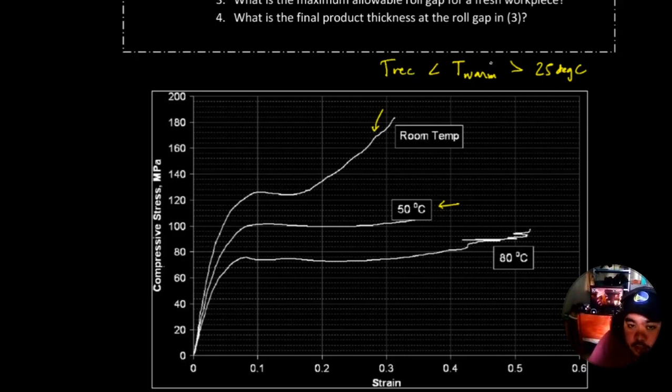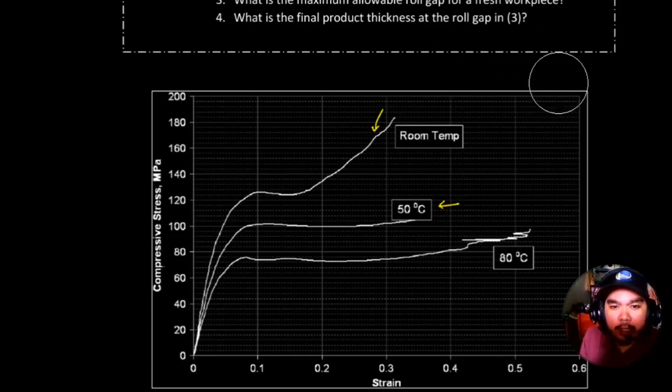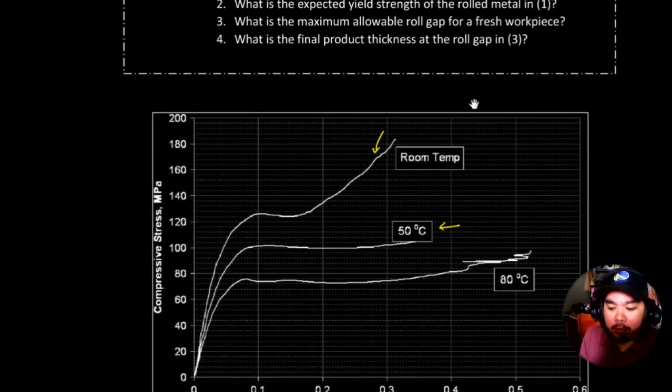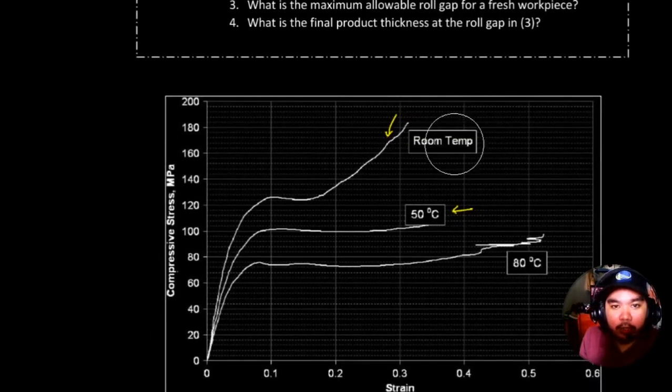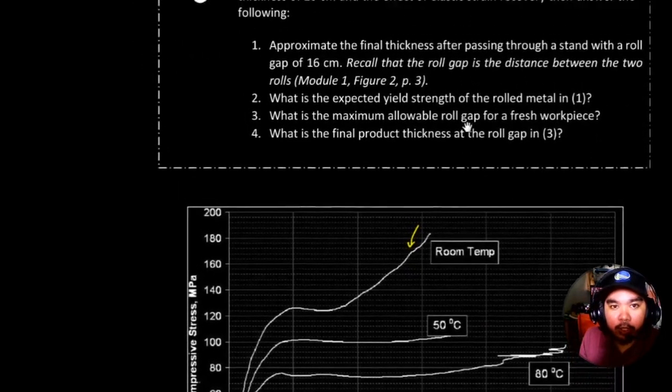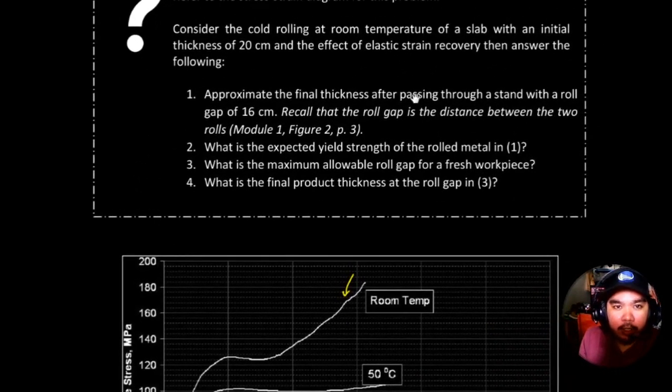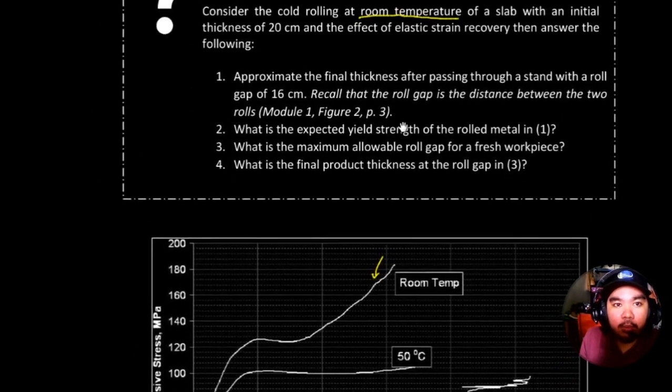But technically, it's still cold working, because you're working at a condition where recrystallization is significantly slower. So we don't really need this. But anyway, we'll use the upper graph because this is our room temperature condition, and the problem says it's cold work, and specifically says room temperature. So we can use this one.